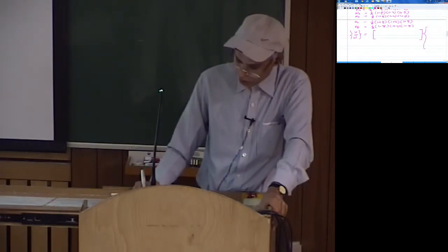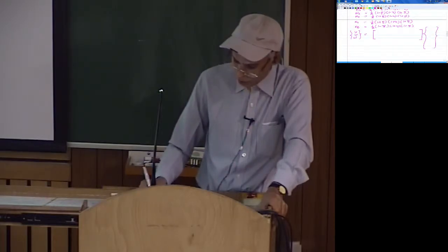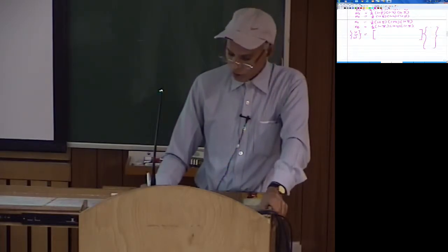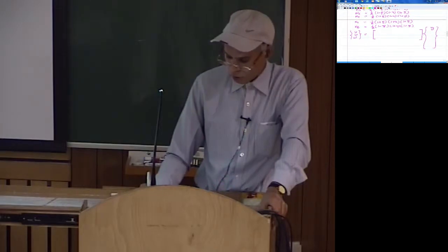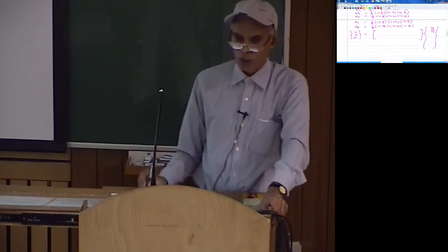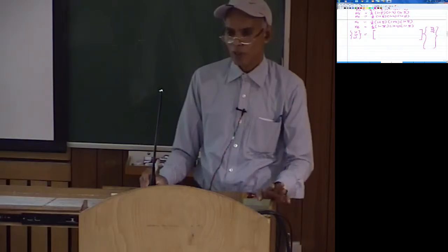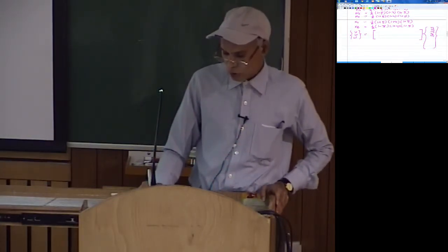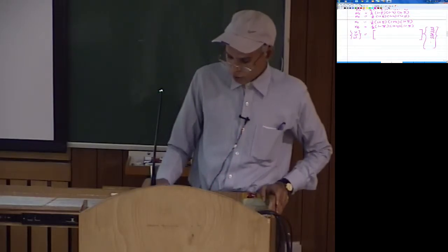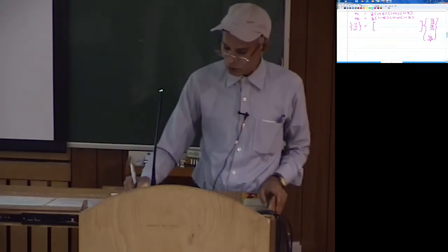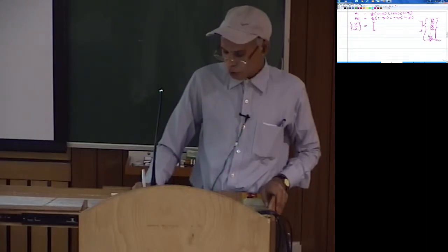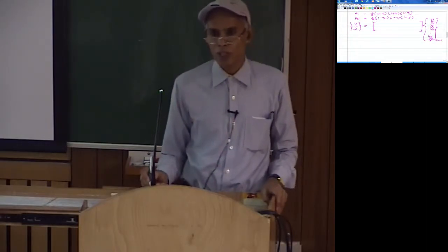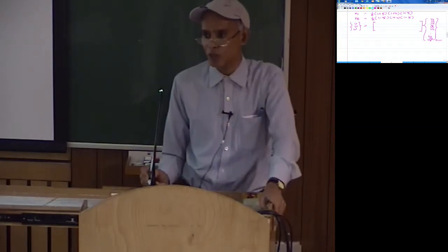Now the arrangement of the vector of elemental degrees of freedom is going to be, first node, say the displacement along x direction u1, v1, w1. So these are the degrees of freedom of the first node, values of displacements along x, y and z directions, then u2, v2, w2 and so on. Finally, we will have u8, v8 and w8. So this is your vector of elemental degrees of freedom. As you see here, this is going to be 24 by 1. So we have 24 elemental degrees of freedom.